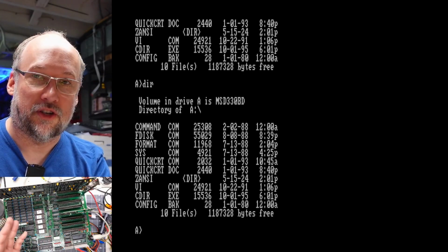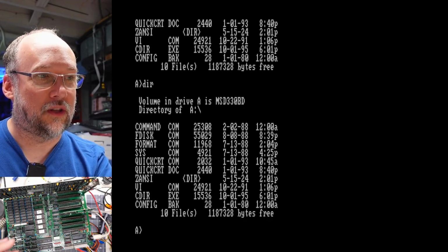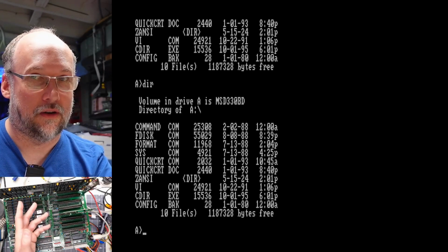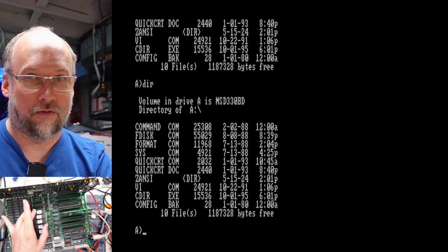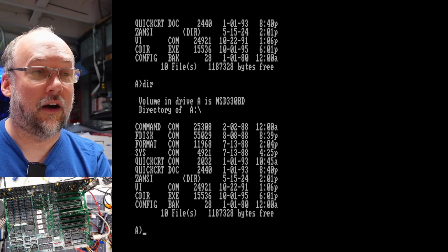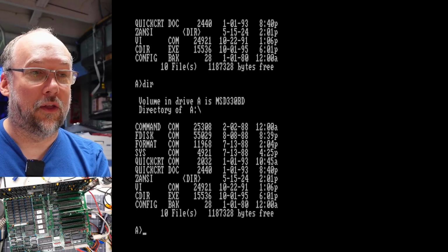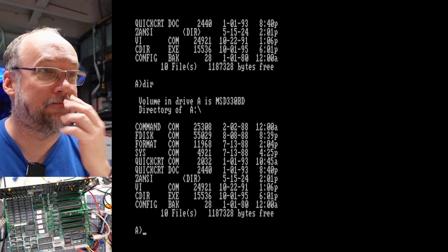It must go to a couple different chips. And maybe if we cut the trace at the right point and we ground the signal going into whatever that chip is, wherever it is on the board here, then DOS will always think there's horizontal or vertical refresh and it's safe to draw, which would speed things up. Now that might break other things, because maybe certain pieces of software wait for that.